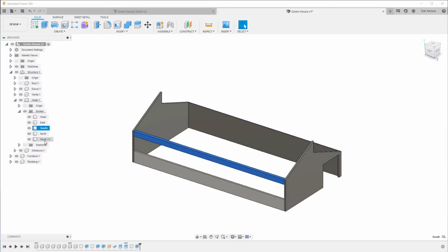Is that a problem? No, not necessarily. Like you can see, they're still referencing each other. When I ultimately went through and built the final model of this, I had these structures tying these two connections together, and it was actually one solid, so it was a little bit easier to turn off. But say this was a headache for me, and I didn't want these two things separated. I could create a new component from this body, so now it's a subcomponent under walls. I could put both of those bodies in one subcomponent and very easily turn those on and off.